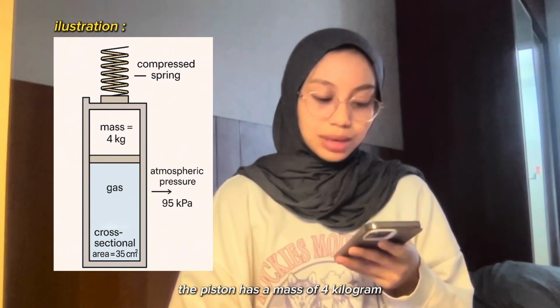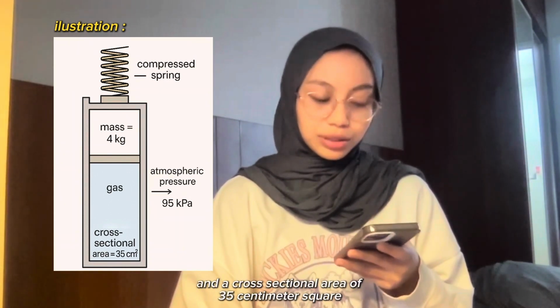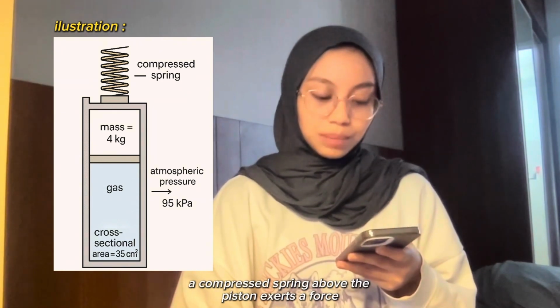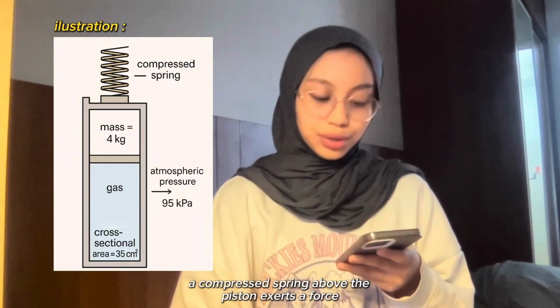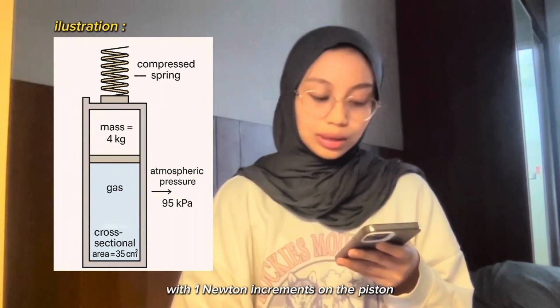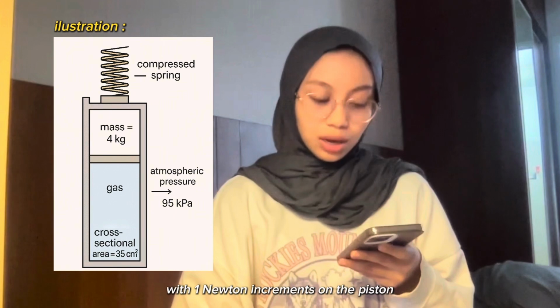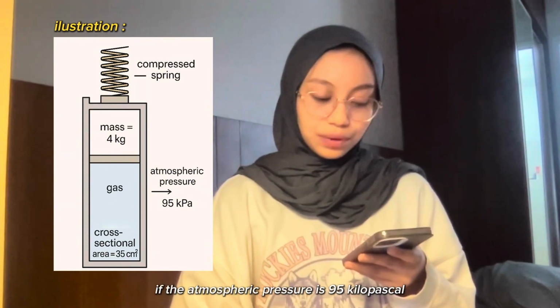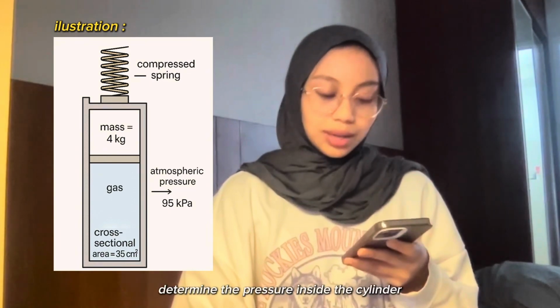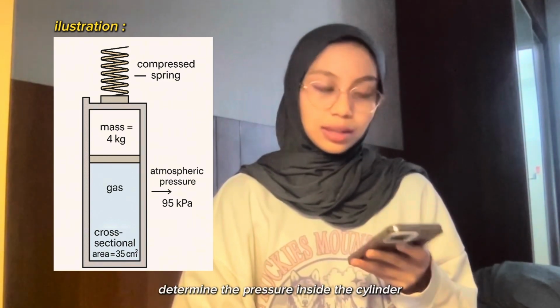Question number 6: a gas is contained in a vertical, frictionless piston-cylinder device. The piston has a mass of 4 kg and a cross-sectional area of 35 cm squared. A compressed spring above the piston exerts a force ranging from 0 to 500 Newtons in 1 Newton increments on the piston. If the atmospheric pressure is 95 kilopascals, determine the pressure inside the cylinder.